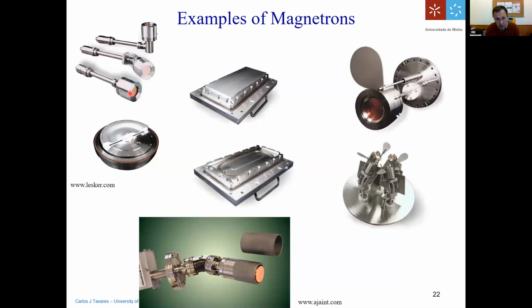When you talk about a magnetron, it means that you have to have the magnets below the target. Otherwise, if you don't have the magnets, you just call it a source, on which you can put a target. So you put the target here, and you have this cup around it in order to protect the underside of the magnetron, which is a copper sheet. It's made of copper. You can have a system with 4 mini magnetrons. Each of them has this kind of shield that you see here, or a shutter, which you can operate externally, and you can close or open it.